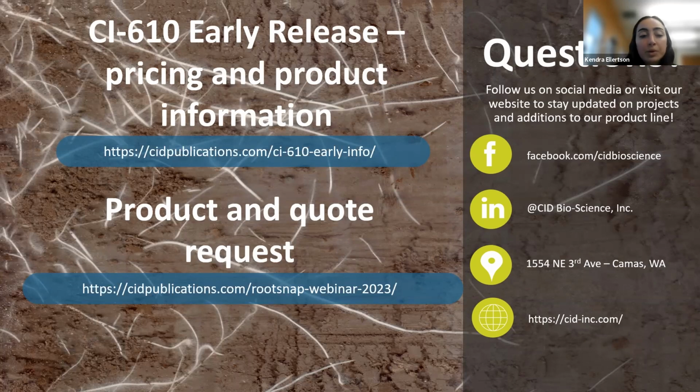And if you're having trouble detecting the difference between dark roots and dark soil, you can also do some image adjusting before you import it into the software. As I showed you, we have those tools to change the image brightness, the contrast, and the gamma. But if that's not enough, you can put your image into a different editing software, adjust the colors and the contrast, and then import it back into RootSnap. So you have a very clear image where you can see the contrast between roots and soil.